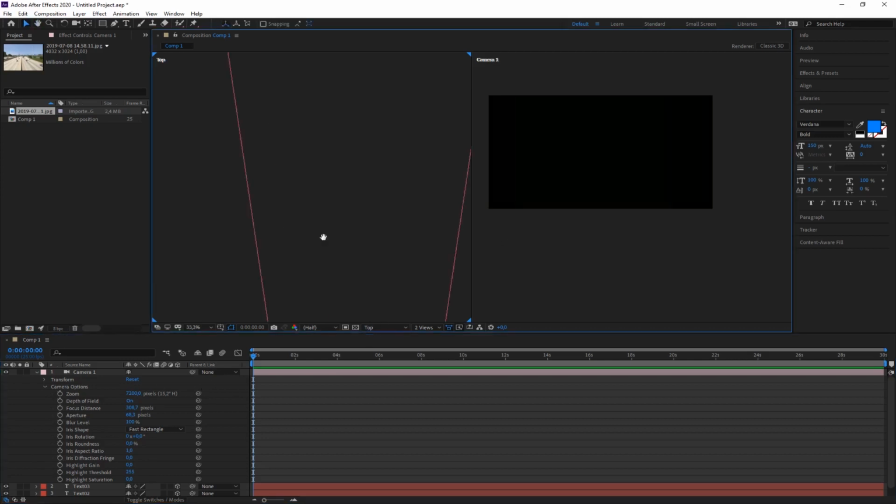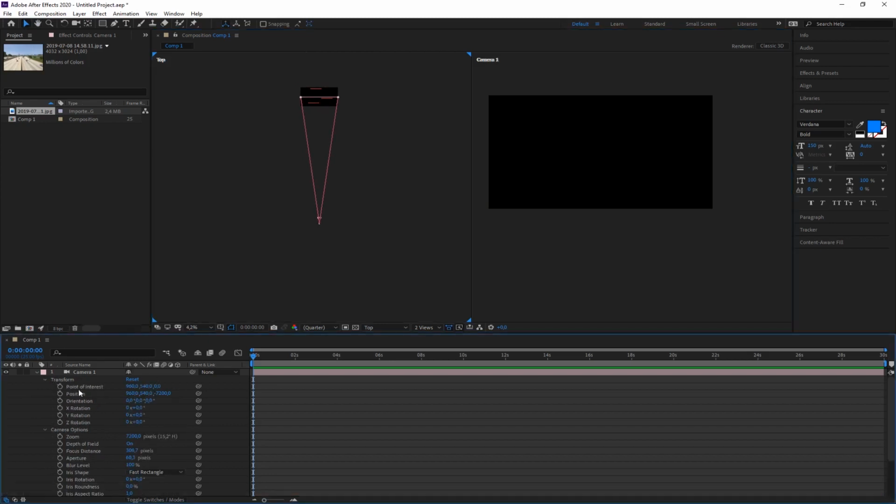For our camera, we can define where is the sharp distance, and right now we are really far away. If you look at camera position, we are position -7,000. So we are 7,000 pixels away from our ideal plane here in the middle. So it only makes sense when the sharp distance is also somewhere around 7,000.